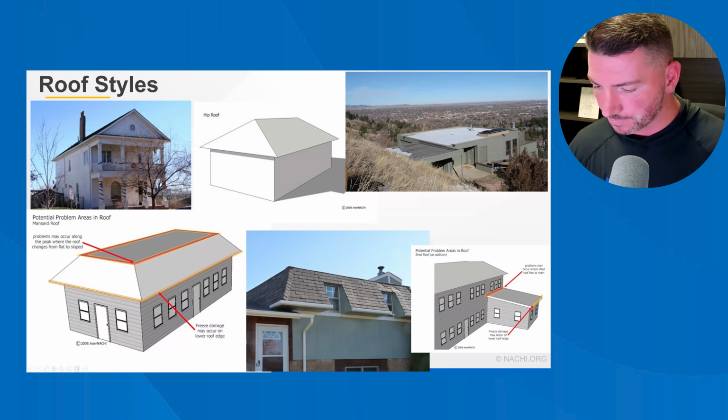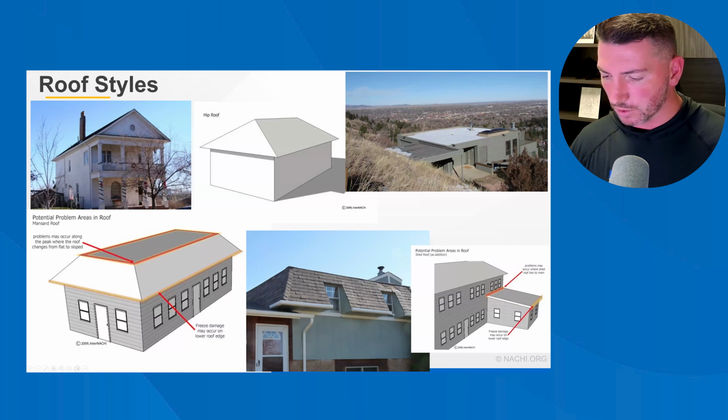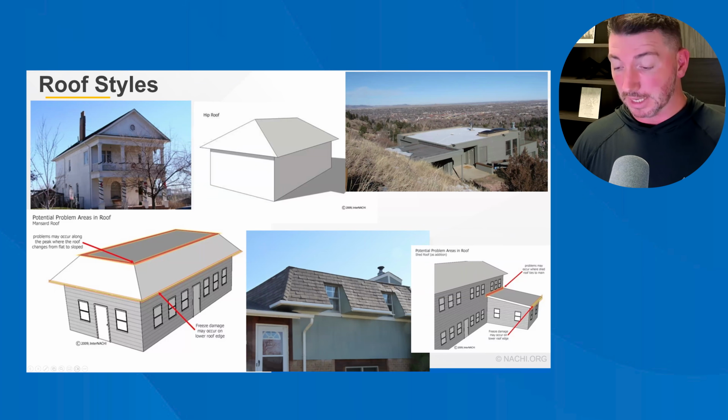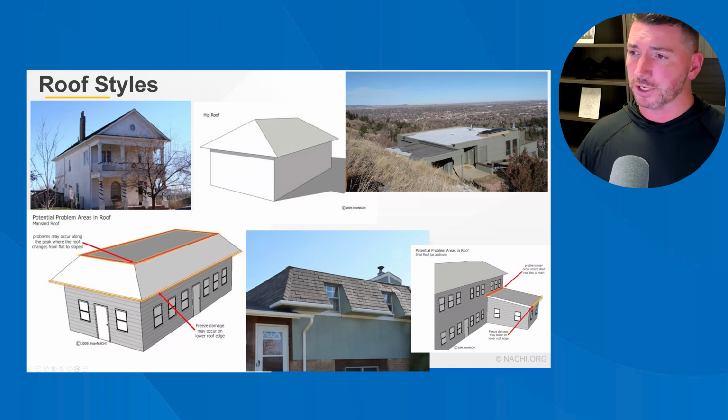Mansard roofs were invented by the French when owners were taxed by the height of the building as measured to the roof eave. They're short, steep roofs installed around the perimeter of what's usually, but not always, a flat roof building. Some of these roofs can be nearly vertical, and this can cause installation problems, which will vary with different types of roof covering materials. And you heard us a minute ago say that asphalt shingled roofs have a lower limit, but they also have an upper limit in terms of normal roofing practices.